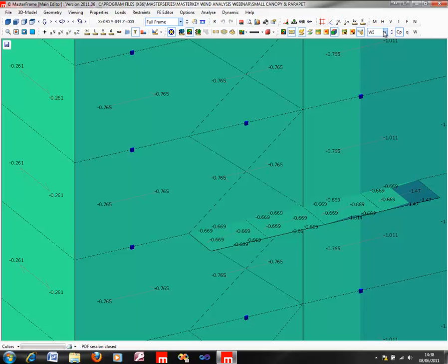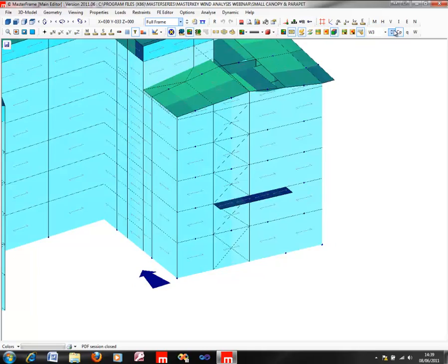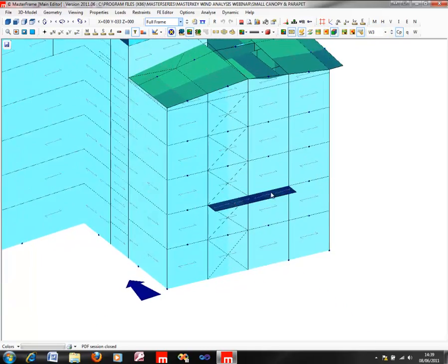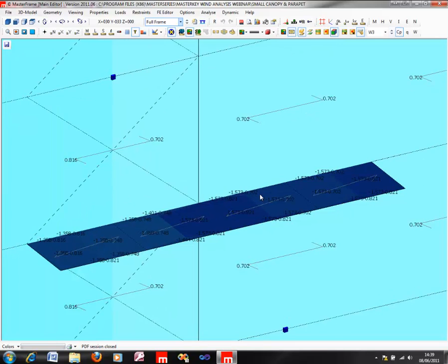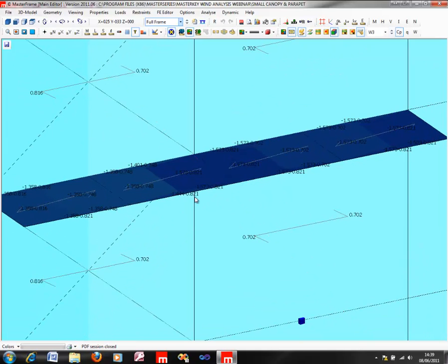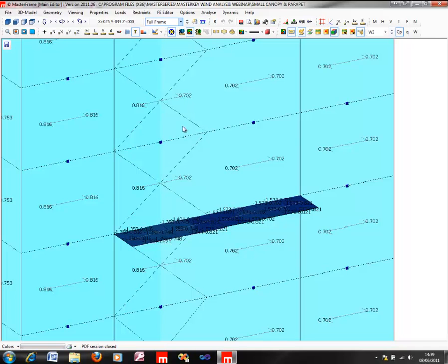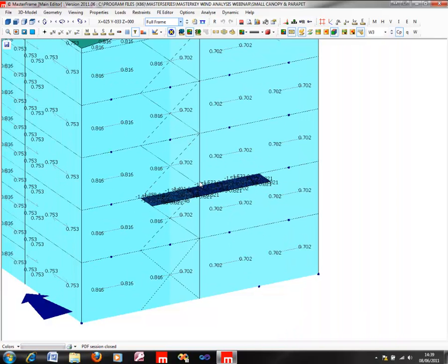And we can see, if I come back to an appropriate wind direction, which is like this, we're getting a similar scenario where we have an upper surface pressure with the lower surface pressure being deducted from that, which is equal to the pressure we get from the wall below. There are different rules in that publication with regard to the height of the canopy on the wall. Whether it's more than halfway up, it's dealt with differently again, and we're adhering to all of those rules.